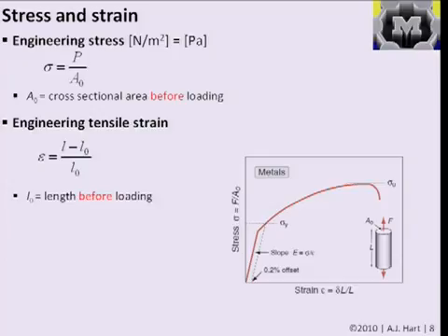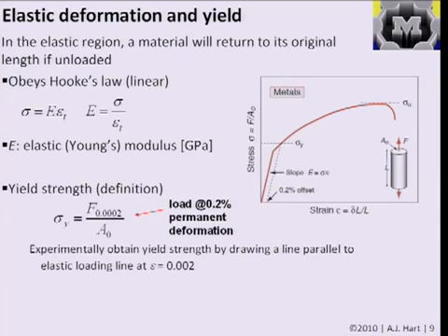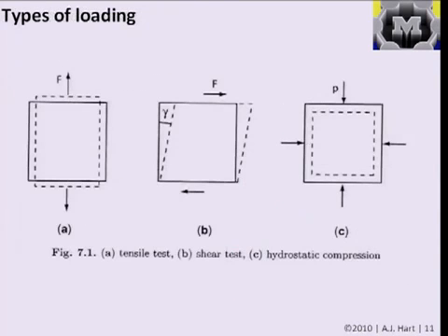And we're just going to think about what happens as we shrink the size of the system down. In addition to the simple case of loading of this uniaxial bar in tension, we can have different types of loads, and we won't treat any of these analytically other than the case of simple tension up at the left here. But we'll see some experimental aspects of how loading nanostructures in multiple directions can lead not only to tension, but to things like shear, where you're basically moving the material at an angle in a direction that is parallel to the load, and also cases where you're applying, for example, uniform or hydrostatic pressure or bulk compression to the material.